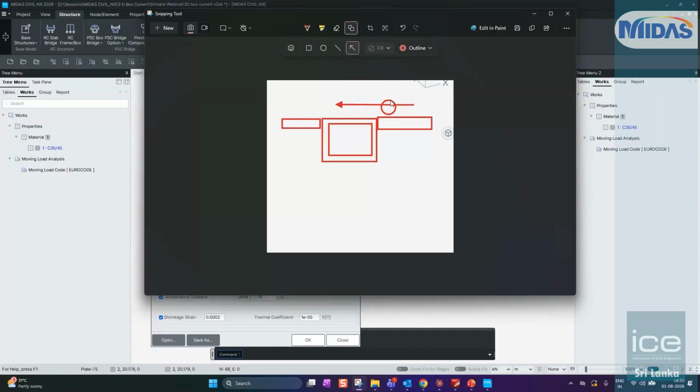So due to this moving load, you accounted for your live load surcharge. But if you constructed a very thick road next to the soil or above the soil next to it, what would happen is that this part of the soil is going to now see a higher surcharge load. Of course some part of this thickness will be replaced by the soil, right? Will be replaced by your pavement. Sorry, probably I should have used a different color.